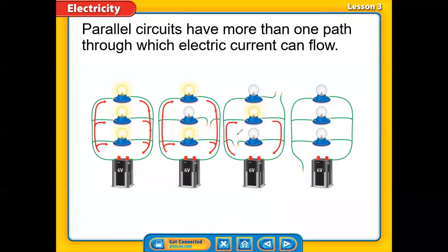In a parallel connection, the current will not be affected, because the bulbs are not sharing the same current, but they are sharing the same voltage. They have different currents. Each one gets the current it needs, because they are directly connected to the source, the battery. So any hard question here, guys, up to this moment?